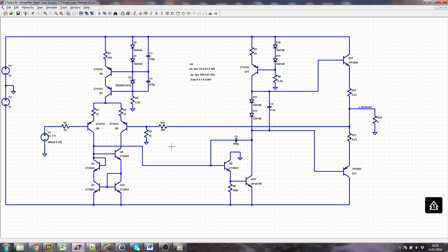The problem sometimes you find with circuits with a global feedback loop around several stages is things that look bad over here can be due to this or this or this or that, or who knows, and it's very difficult to pin down what's actually at fault. Takes a bit of experience. So we want the resistance looking out of this base and the resistance looking out of that base to be the same. So the base current that flows jacks the base off the zero by the same amount on either side, so you get the same VBE change due to the base current flowing through these resistances, and that means you don't get any imbalance due to the base resistance looking out being different.